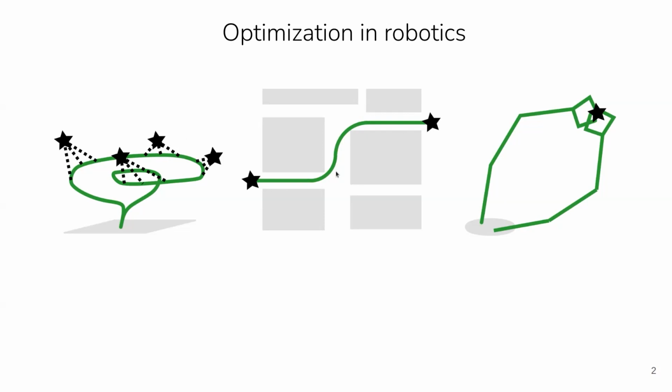In motion planning or in trajectory planning, you might be given a start and an end point and a map, and you want to find the best obstacle or collision-free trajectory that combines them, potentially under some time optimality or cost optimality functions. And to the right here, we have inverse kinematics problems, or more complicated planning problems where you have, for instance, redundant robots, where often you will also pose this as an optimization problem. And here the particular thing is that you might often have multiple solutions that actually are the global optimum.